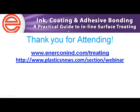The only downside, really, to using something, it could be a primer, an IPA wipe, it could be really anything, putting something on the surface after plasma treatment is you're pretty much going back and contaminating it again. More often than not, if you do anything to the surface after plasma treating and before bonding, you're going to actually hurt the process more than help.